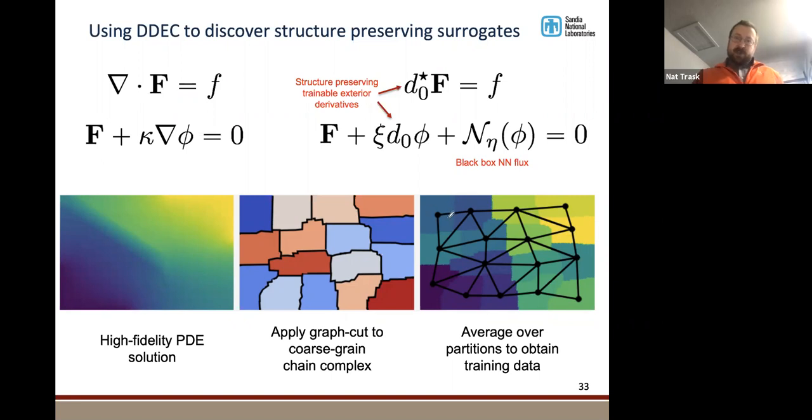And your training data is that for each node of this mesh, you'd like it to reproduce the moments of your high fidelity simulation, right? So you'd like something that's cheap and low dimensional, but it inherits the accuracy of your high fidelity model. And in a certain sense, this is like a reduced order model, but the workflow is totally different. This is based on a control volume analysis rather than the usual do PCA, do a least squares residual minimization and so on that people do in ROMs. So there's a lot of consequences of that.